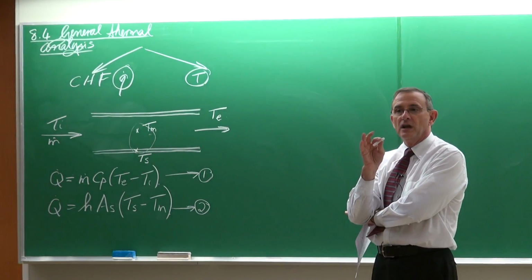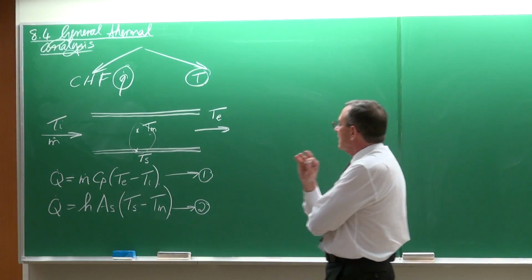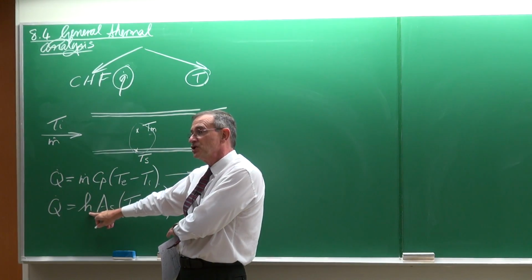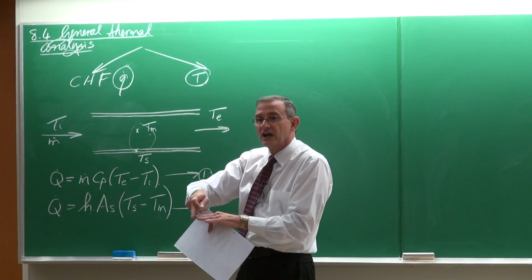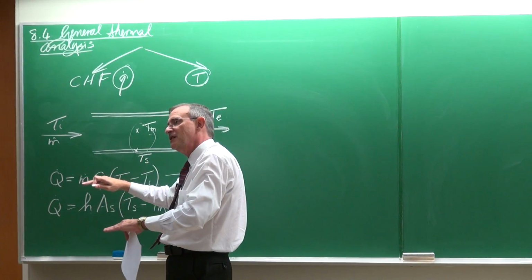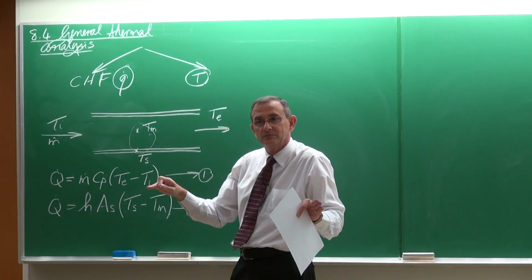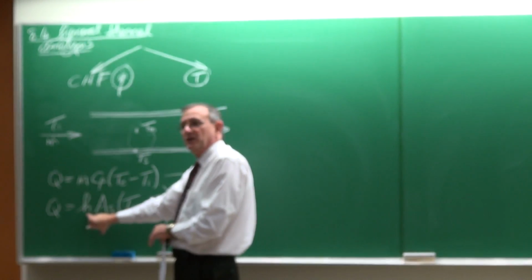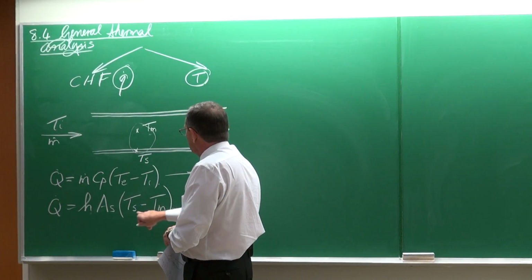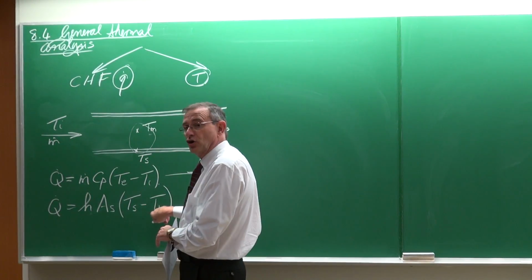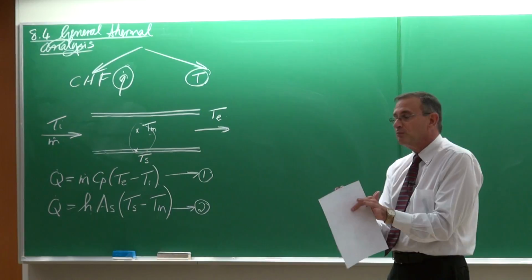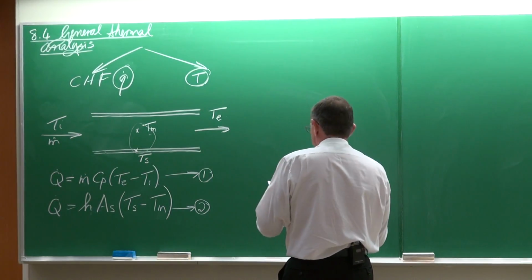However, if you think back of the lecture of yesterday, the thing that complicates this is the heat transfer coefficient. Because the heat transfer coefficient in the lectures of yesterday, I've showed you that the heat transfer coefficient at the inlet is very high, and then it would decrease until it is fully developed. So it is not always a constant. Okay. So this might be a constant, or actually is a function of x, and these temperatures are not constant because they change depending on the fluid temperature. So that is the complications that we have to consider.